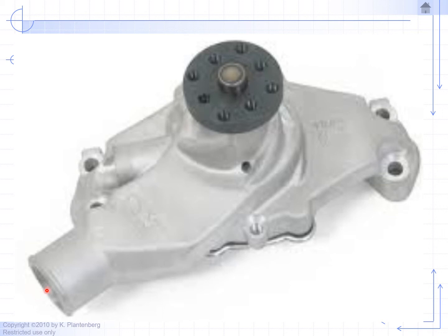You can machine the hole, for example, here where the water hose attaches to. You can machine the bottom where you have this foot, and you have another foot here. You machine it so these two surfaces are parallel and coplanar, and then you can mount to the front of the engine block, and you want a nice seal. You don't want anything to leak as far as water coolant. So the bottom of these two feet you will machine so you have a nice smooth surface, parallel and coplanar to each other. And also you want the bolts, when you bolt it onto the engine block, to go in perpendicular to the engine block.